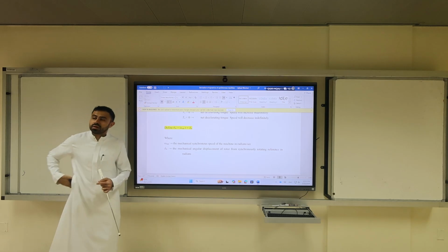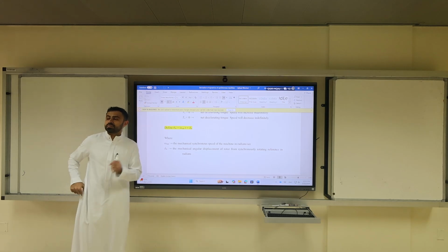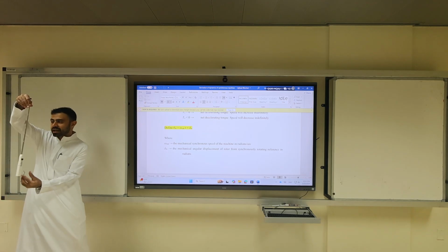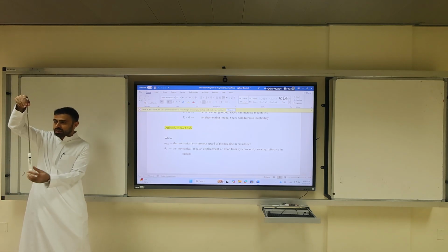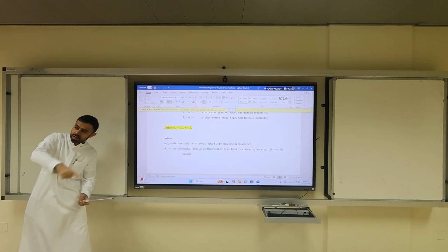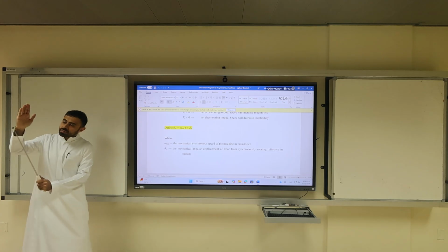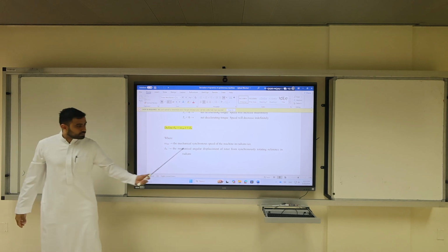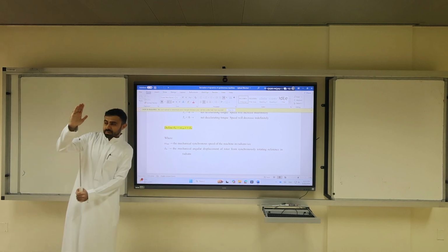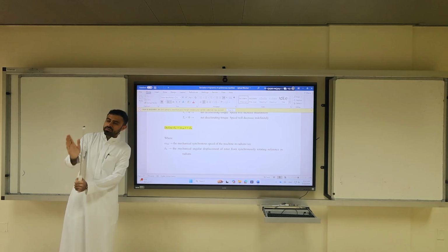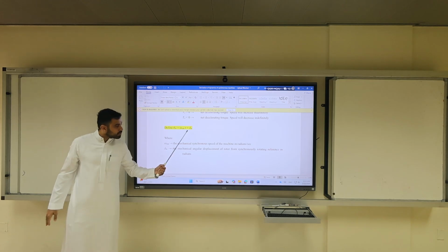Rotor. No, the magnetic field, which one is rotating by itself? The stator. So the rotating magnetic field would have an axis corresponding to the peak. The peak would move across the perimeter of the machine. The displacement between the rotor maximum point and the maximum point of the stator is delta m at time 0.